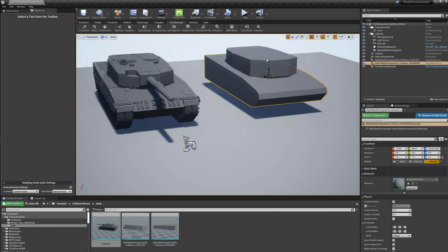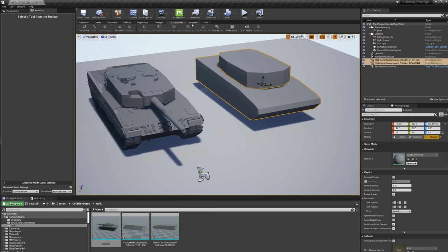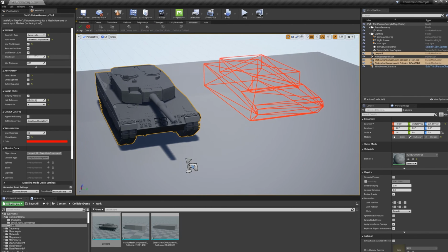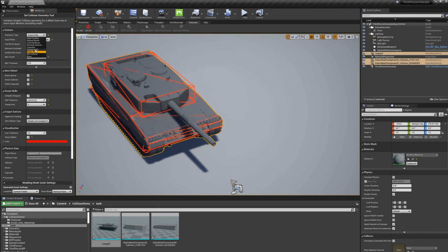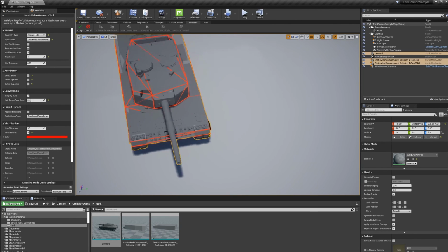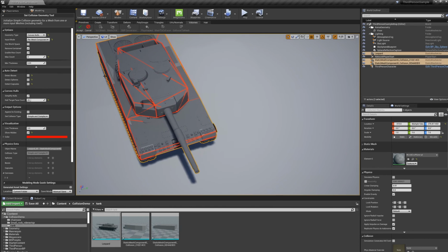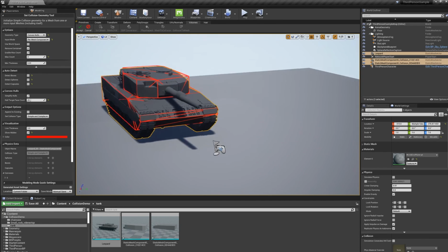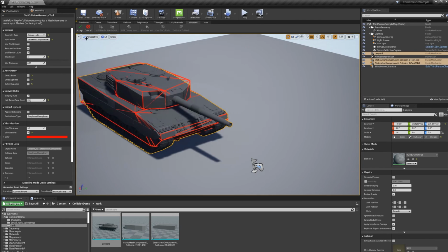I mean, if I only cared about those two main pieces, then I can just select those two and this one, and do mesh to collision, and it's going to use those pieces. Uncheck world space because their pivots are all the same, and if I made the things with swept hulls, I can use convex hulls to reproduce them. We don't automatically detect convexes, but if you use convex hulls on convex hulls, you're going to get convex hulls out. So now I've got those two main body pieces.